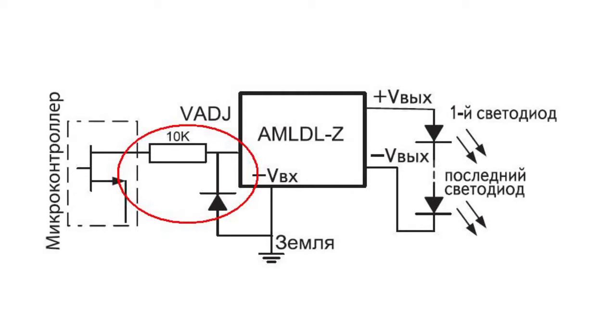It is necessary to remember that the frequency of the PWM signal is to be no less than 100 Hz to avoid visible flickering, and no more than 1000 Hz, which is the maximum bearable frequency of the PWM signal